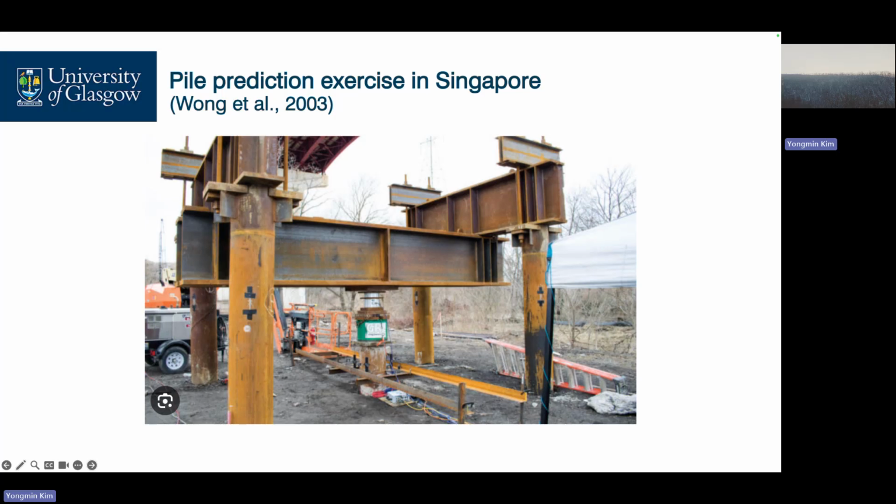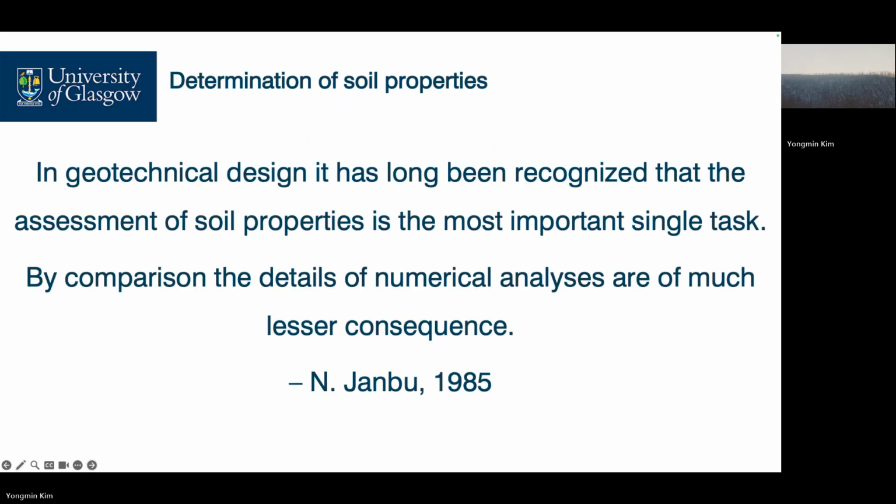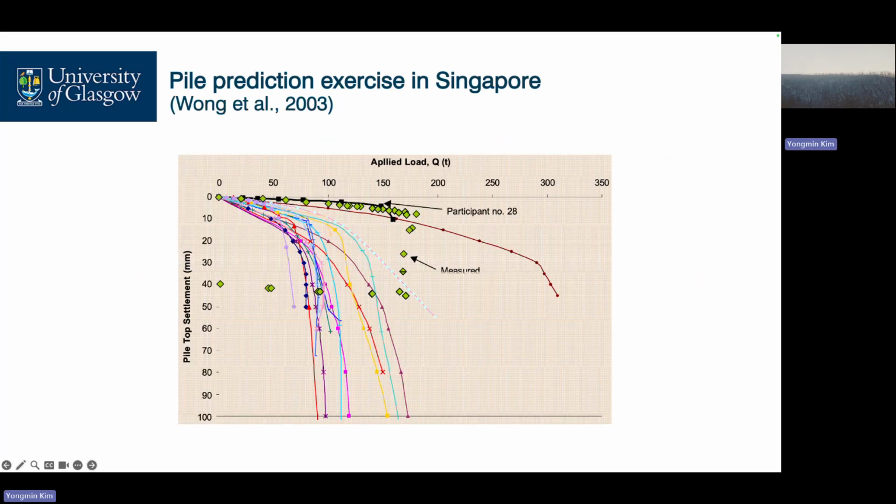Press down. Then all strain gauge readings are recorded. We also record pile head settlement. So we will get such load settlement curve, load transfer curve.